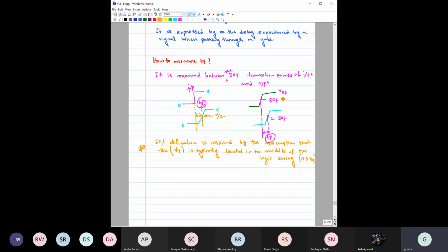So yeah, in the context of this digital IC, we would like to also have it like this. Suppose in case of this CMOS inverter, it is like this, right? When you are considering charging of this output load capacitor, the output will charge from 0 to VDD, and while it is changing it should charge through this PMOS only, then this is off, and in that stage the input is like this, right?